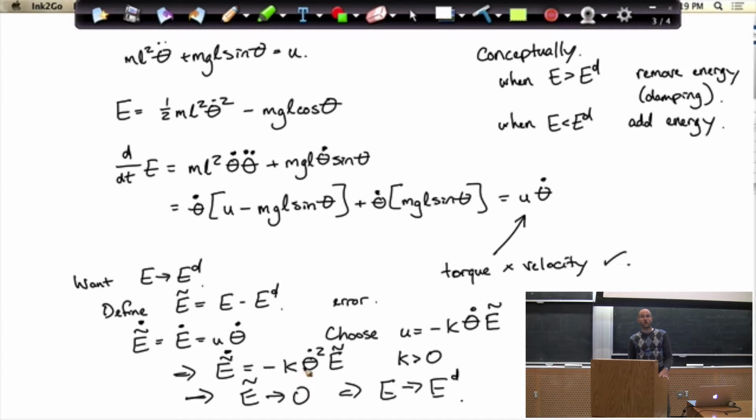That would work. Sure. And I think the only possible motivation for this is the smoothness of your control. You have a nice smooth control function as a function of space until you flip once to your LQR, as opposed to a sine which is going to go to zero and potentially flip. Yeah, I think that's a totally reasonable suggestion, and it'd be easy for you to try in the code.